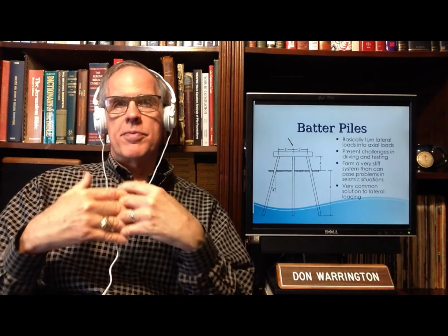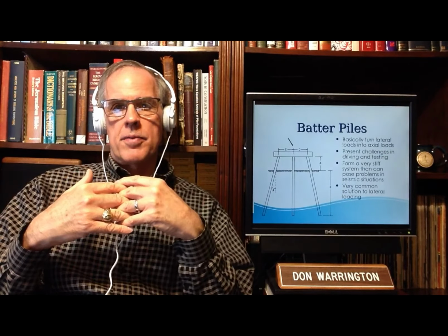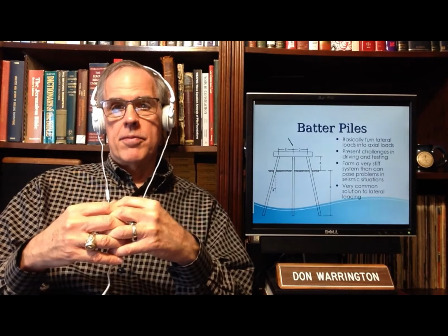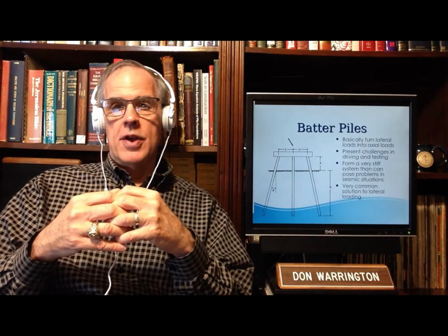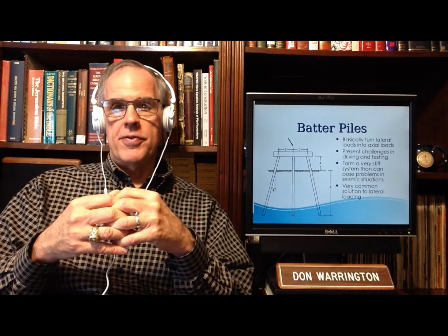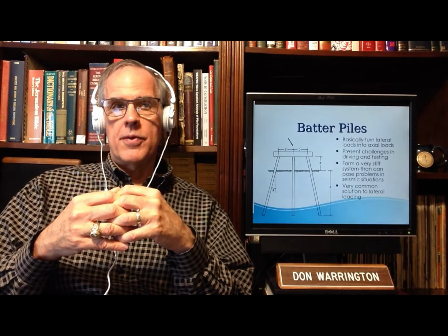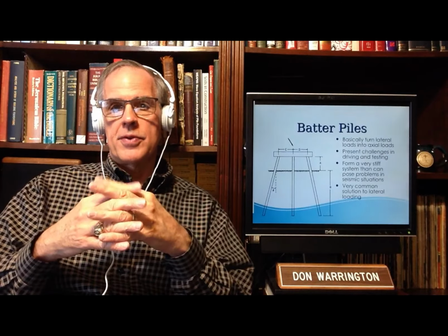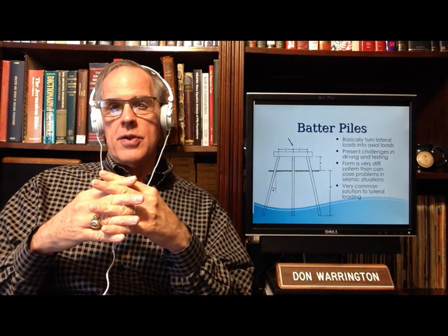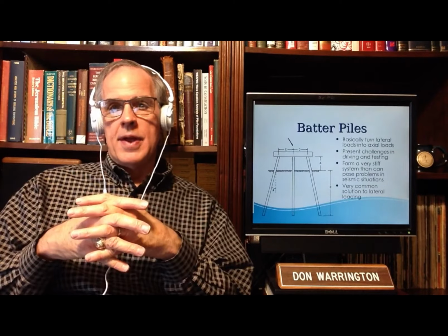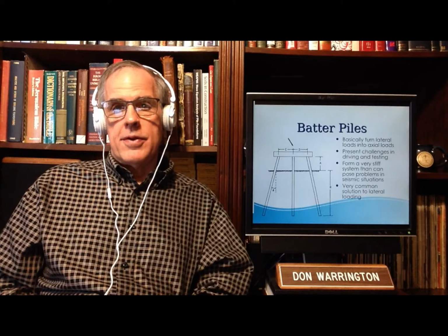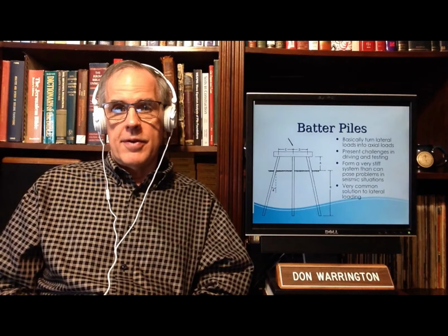The problem with batter piles, well, there are two reasons. One of them is they can be a bear to install. I've been involved in many projects where the batters are sometimes severe, reaching 1 to 1, and 2 to 1 or 1 to 2, depending on how you express that, or 3 to 1, and getting the equipment to install these can be a nightmare in some cases.